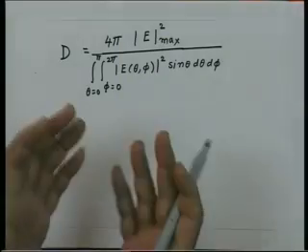And in fact, since again we are going to take the ratio of these quantities, even the absolute value of the electric field does not matter. So, even if we take a normalized radiation pattern with maximum electric field equal to unity, that means E max by definition is unity, the directivity D will not get affected, because whatever the constant is, it will get cancelled.